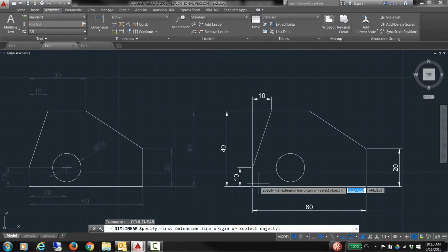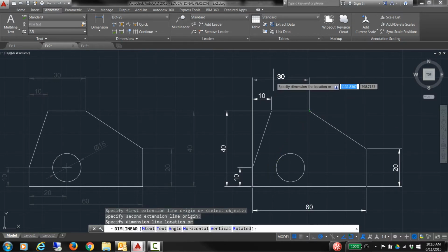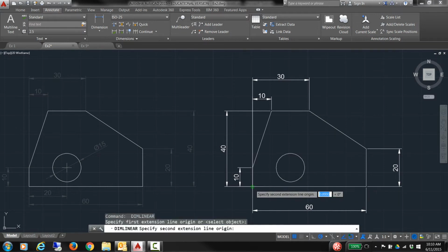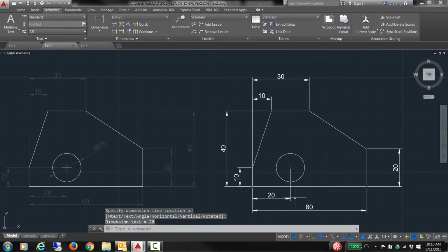And so we're putting in the remaining dimensions here, like so. Remember to keep the larger dimensions over the top of the smaller dimensions so that they're subsumed. That's the correct terminology.